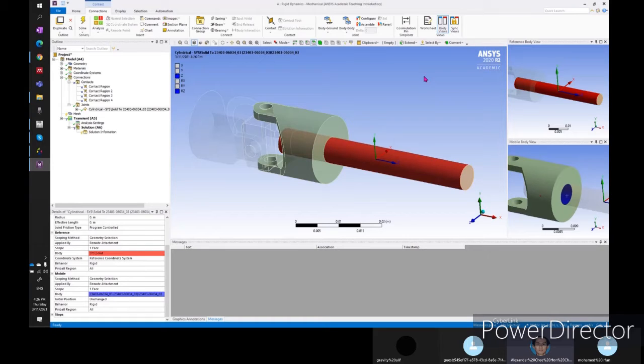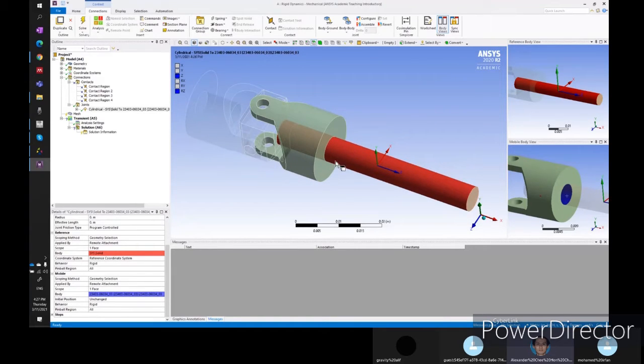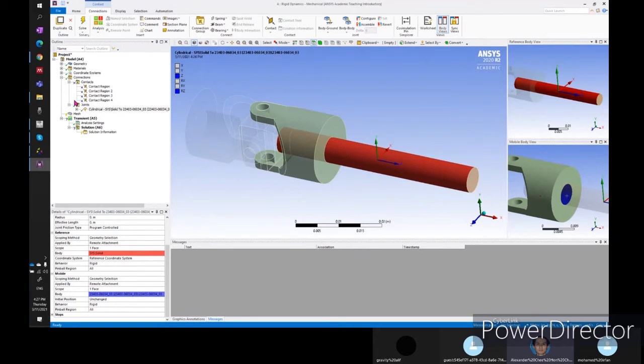Normally, the practice in the industry is I may use SolidWorks to design. But when I want to change the design, to fine-tune it based on the simulation, then normally I will use the internal 3D modeler of the simulation software. And here is the base clamp. Okay, so now this is done. You can see that under Joint, a folder started, and here it shows the cylindrical joint being established.